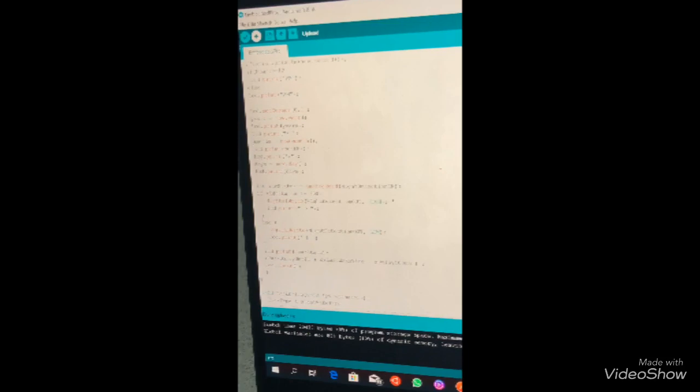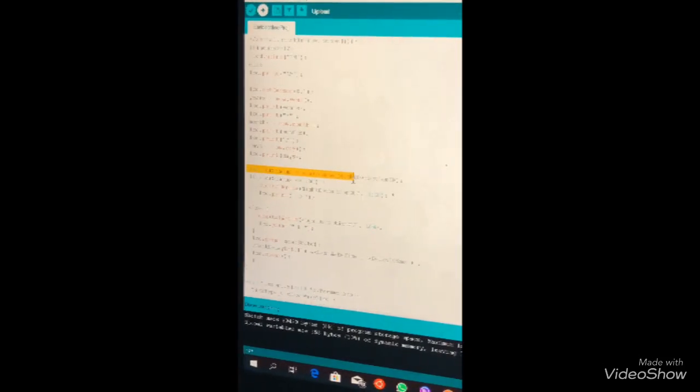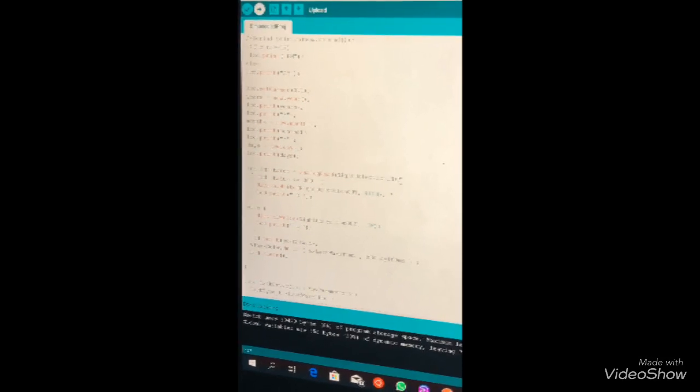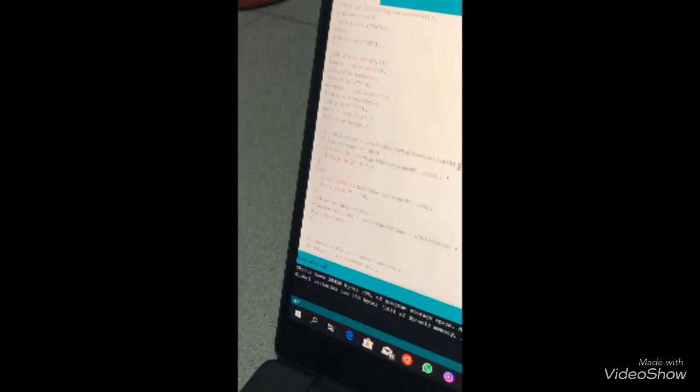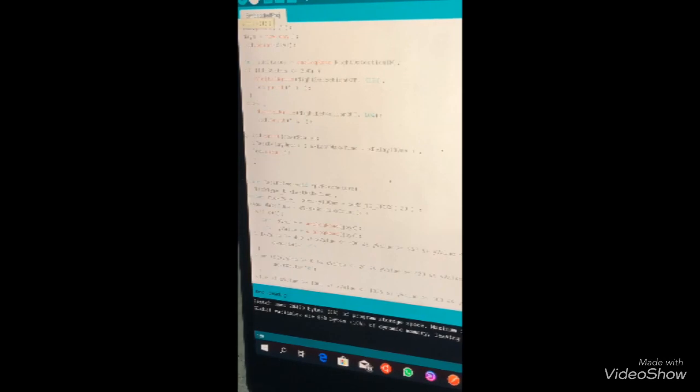And here is the night detection sensor, the LDR status, which reads the night detection pin, which is initialized at the start of the code. And here is the checking of the LDR status, whether it's night or day. If it's dark, we display D on the LCD, and if it's bright, we display L on the LCD. And also we display the gear state on the LCD.